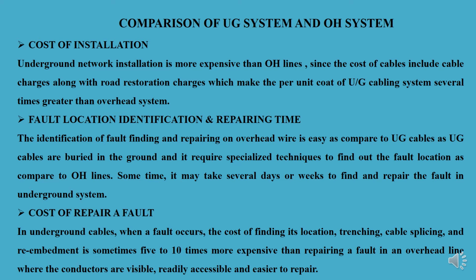But as compared to overhead lines, it is very difficult to identify the faults, and it requires more time to repair. If it is overhead, it is visible, we can identify the fault easily, and we can repair easily, right? So much more time is required for repairing and for identifying the faults in case of an underground network system.